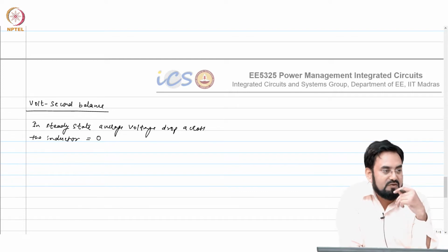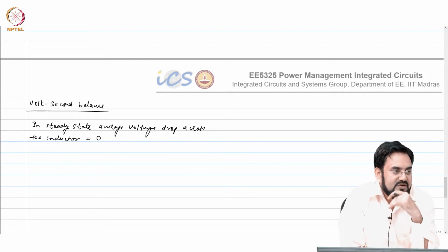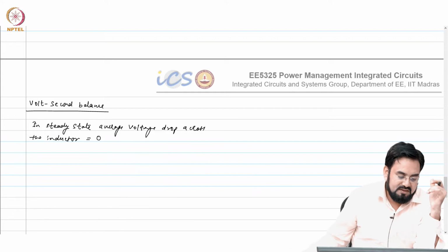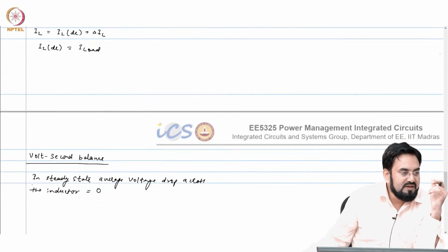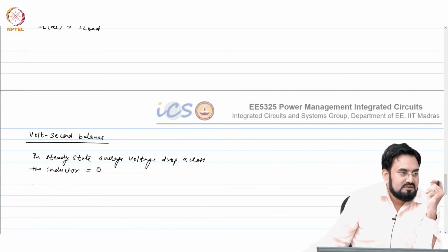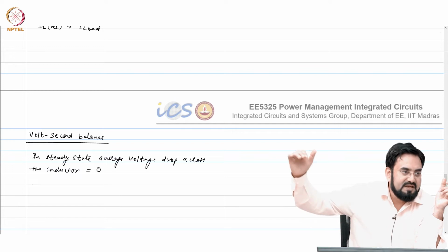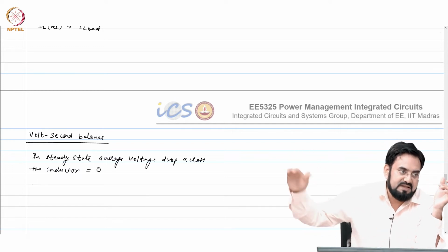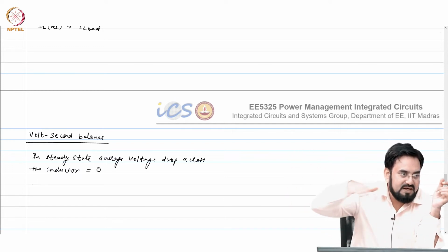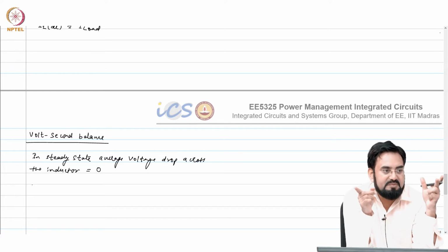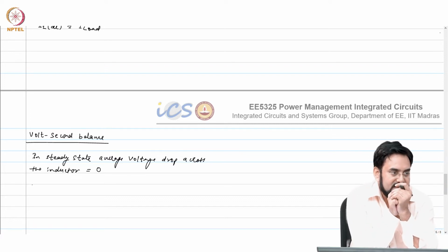And this is required to have a DC current, because we know that current is an integrated voltage. So, if you apply any difference, it will keep integrating and current will never stop, it will keep rising. So, in order to have a current settled, the voltage must be maintained 0 across the inductor.